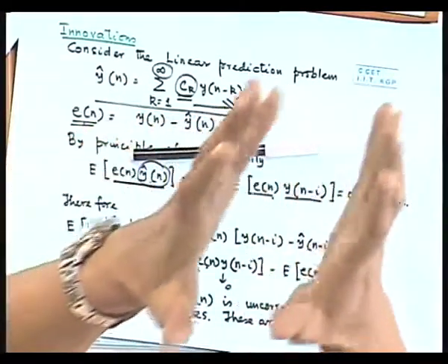We said that if you have a data sequence y1, y2, y3, y4, it has some information. We had said that we can transform this vector into a set of innovations which will contain the same information as this sequence, but between them they will have no information overlap. That is, E1 will have some new information, E2 will have some new information, E3 will have another new information. Together, E1, E2, E3 all together, they will contain the total information which is there in y1, y2, y3 up to yn. Only thing is that information is now compartmentalized, which is not there in the y's, right?